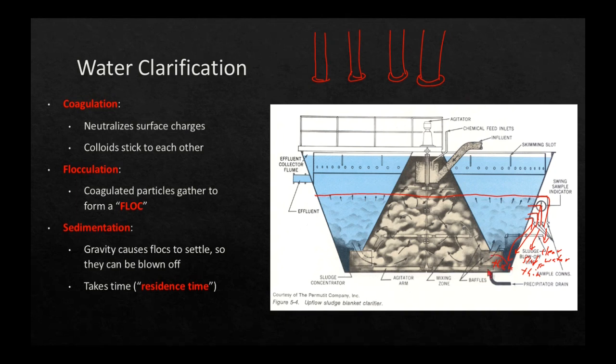So this one here is going to give us thick sludge, and so we're going to fill it up to the 200 milliliter mark, and maybe we're going to wait 10 minutes, whatever the procedure says, and we're going to find that the sludge level is quite high, and maybe there's a tiny little bit of water on top of it.